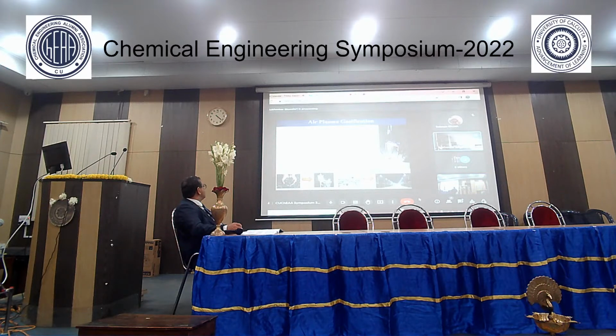Air plasma gasification is a chemical reaction between carbon, hydrogen and oxygen at high temperature. And in any chemical reaction, two things are important: one is kinetics, another is thermodynamics. In plasma, both kinetics and thermodynamics are in favor. Because of such a high temperature, kinetics will be automatically favored. And since we have electrons, ions and excited species, the thermodynamics will also be favored. So overall, it provides a superior thermochemical environment, not only for gasification but for any high temperature chemical conversion.